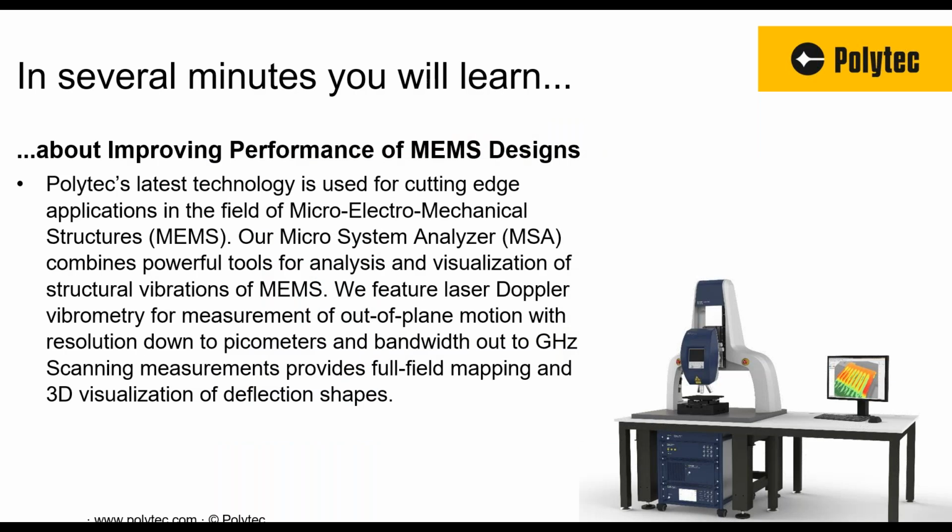If you want to scan and map out the deflection shapes, depending on how many points, this could be tens of seconds to minutes to hours, depending on what you want to measure. So typical measurement, say of 100 points, could take several minutes. If you want to measure 30,000 points, looking at wave propagation going across the screen with micron resolution, some of those measurements could take up to an hour or so to have that level of detail. So we measure point by point. So really the measurement depends on how many points, what frequency, and what sampling time you have.